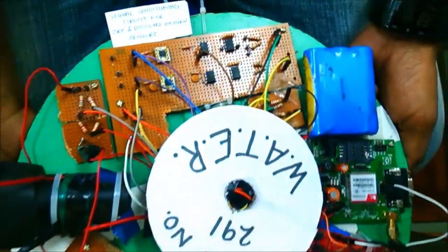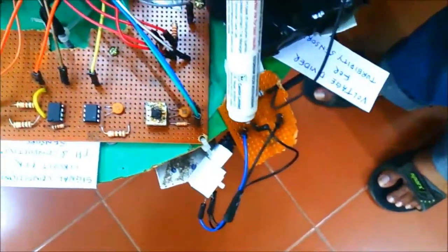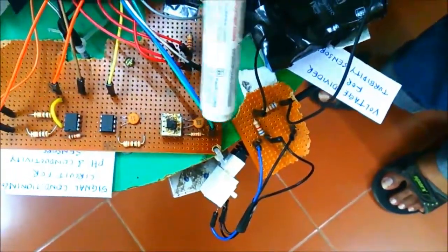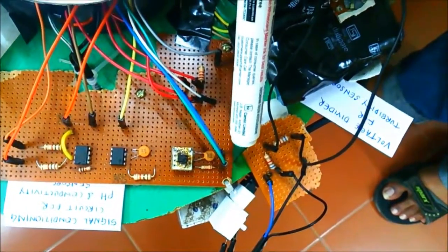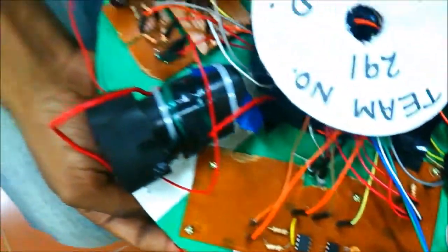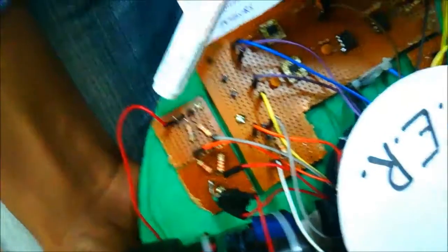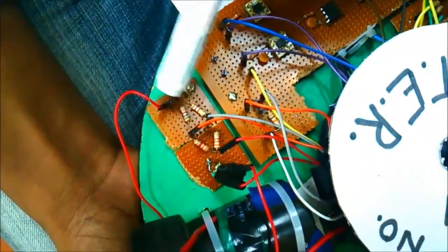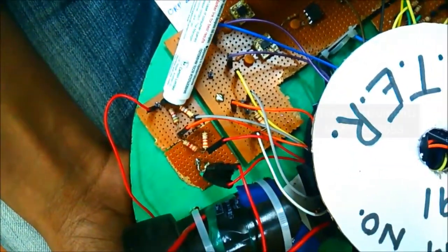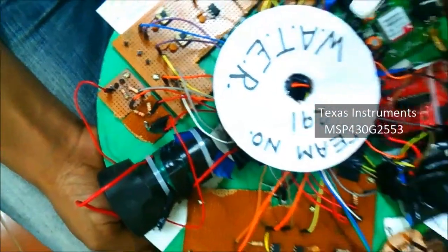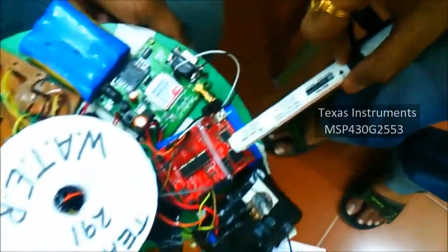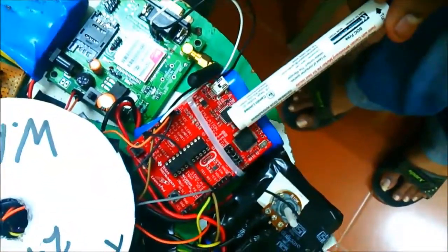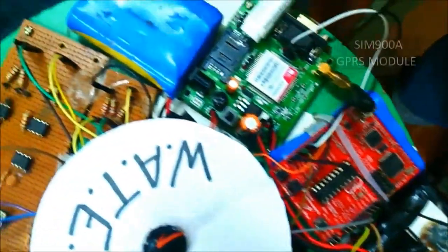The second type of signal conditioning unit is a voltage divider. We have used a voltage divider for the turbidity sensor because the output of the turbidity sensor was very high. The second voltage divider which we have used is because the output of the conductivity sensor and temperature sensor was in resistance. All these values from the signal conditioning unit are fed to the MSP430 launch pad, which processes it and further sends it to the GPRS module.